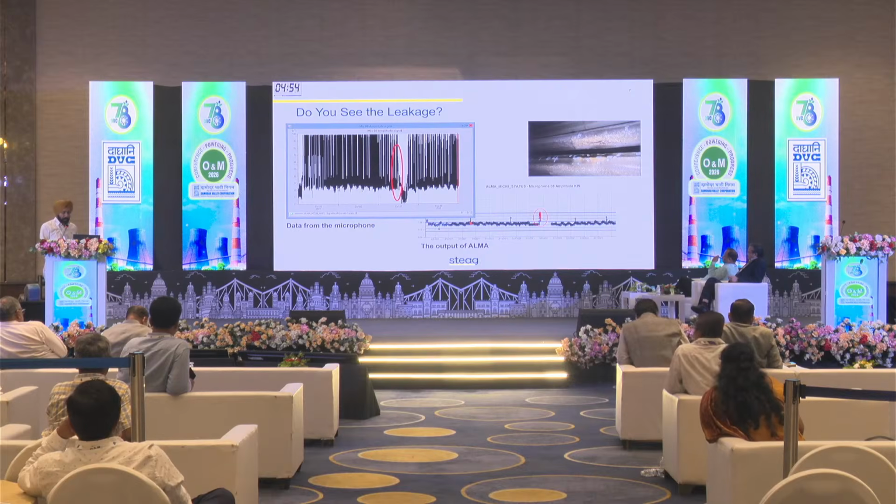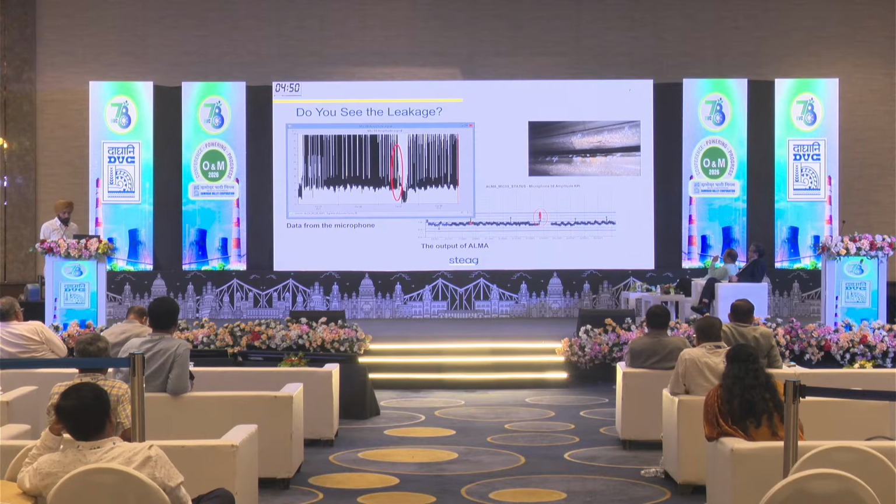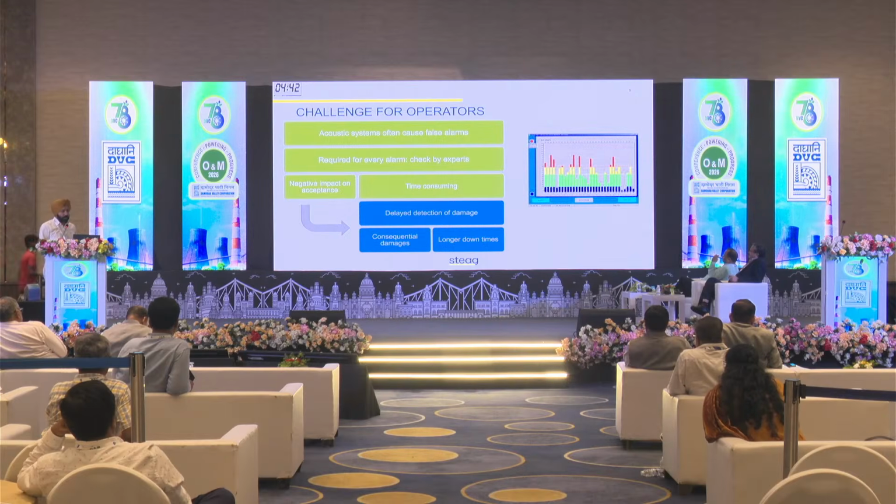And then the action has to be taken to shut down the boiler, depending upon, of course, the commercial conditions, or to still continue with the operation. These are the challenges for the operators, because often the ASLD system gives false alarms. Maybe soot blowing is happening and it's giving an alarm, or some other acoustic noises are present which can also lead to alarms.